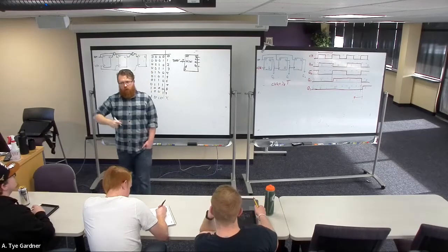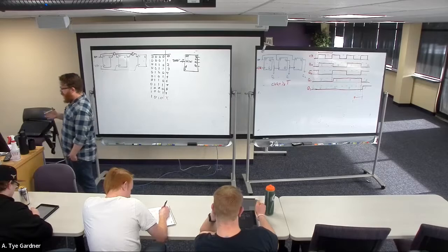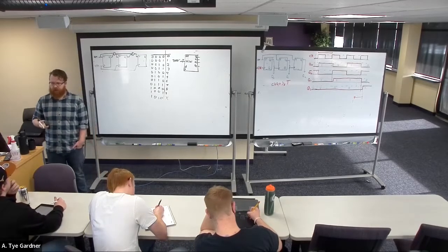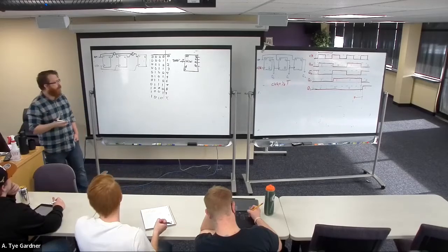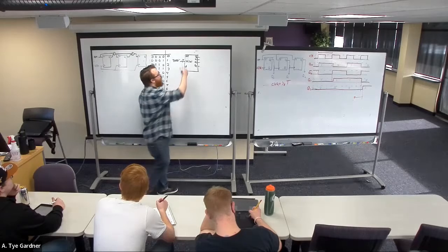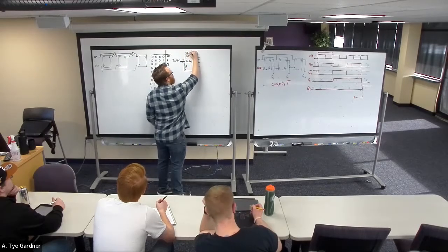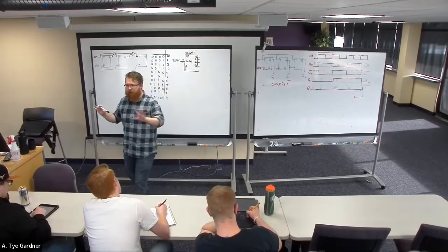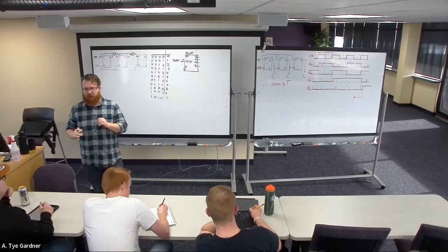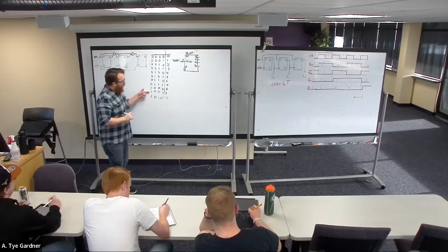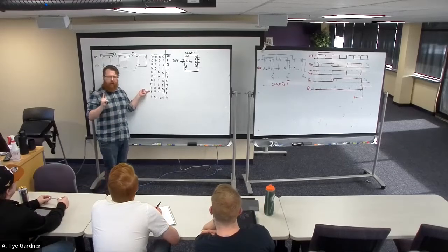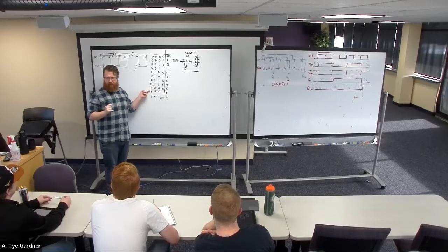We now want to talk about the idea of combining sequential logic with combinational logic. We want to utilize them both. So what this is saying is this is going to be just a 4-bit counter. Nothing special. It's not itself a BCD counter, but I want to turn it into a BCD counter. That means I want to go back to 0 after I see this number. Not when I see that number, but after I see that number.